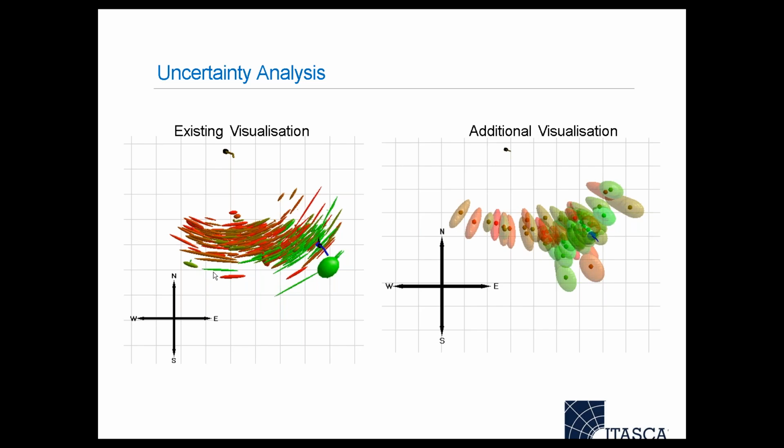One of the criticisms that we received in the past is this: imagine you have 1,000 geophones and now you downgrade that 1,000 to 10. The residuals will be reduced because you can fit your model better since you have fewer observations. But that doesn't mean your uncertainty is reduced. To address this problem, we are introducing this new uncertainty analysis tool. It's not completely based on the residual. It's based on the so-called Bayesian network. You specify a priori uncertainty, how confident you are in your data first, and InSite will tell you the confidence that you have in terms of the location.